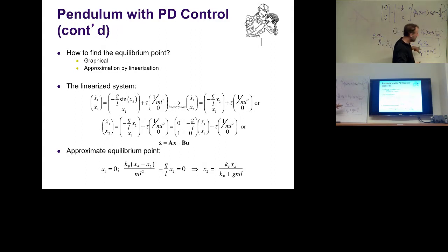Now, this is not what we got, okay? x2 equals all kinds of stuff, multiplying times x desired. We can make this a little bit clearer, actually taking the x desired as a multiplier out of this fraction. Let's just write x desired, look at it like this. So essentially, x2 equals x desired, but there is a pre-multiplier, which is annoying.